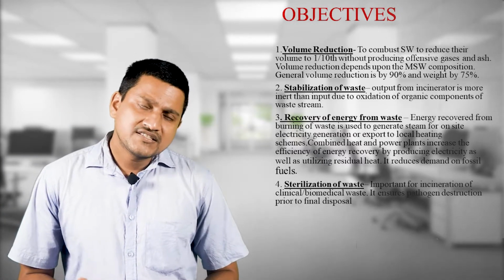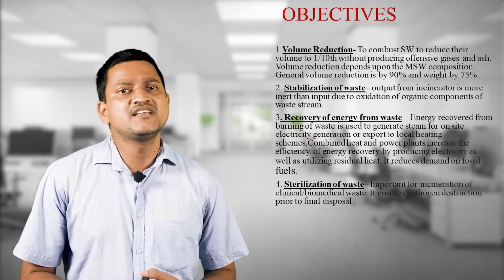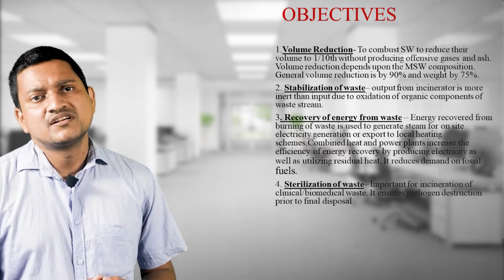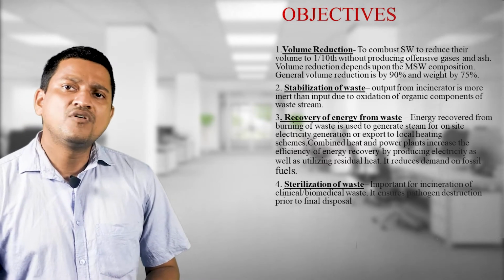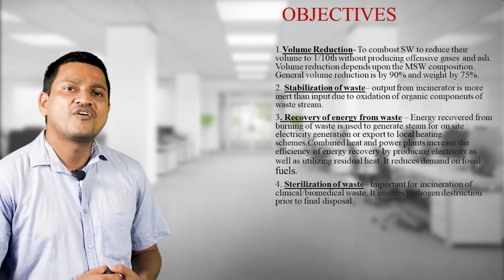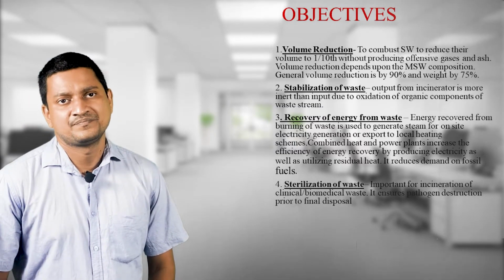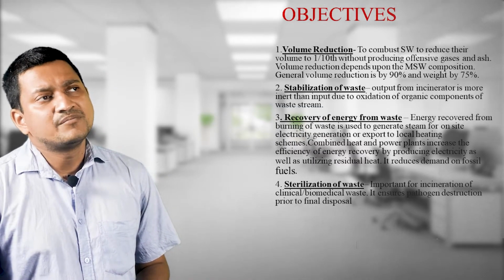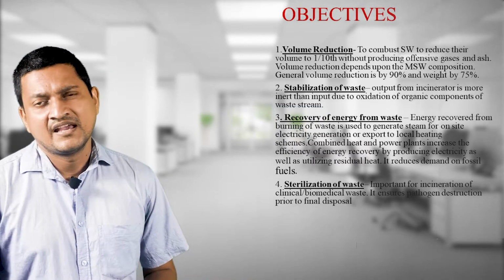Another objective of this incineration is the stabilization of waste. Output from the incinerator is more inert than input due to oxidation of organic components of the waste stream. Third one is the recovery of energy from the waste.